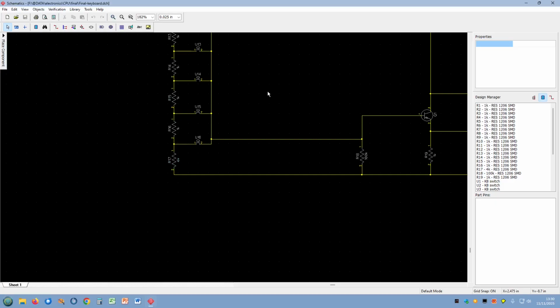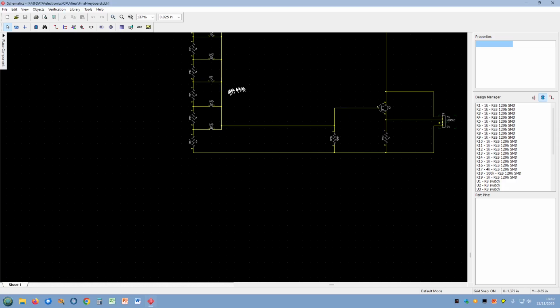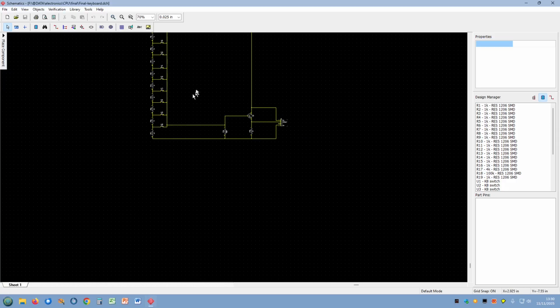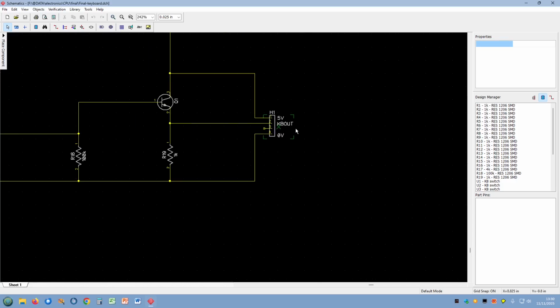If your supply voltage goes down by 10%, the voltage on these will go down by 10%, but this voltage drop across here won't. So different supply voltages do affect it slightly. What I've done is I actually measured it and then calculated what values should be coming into the analog port on the microcontroller and adjusted it to match.